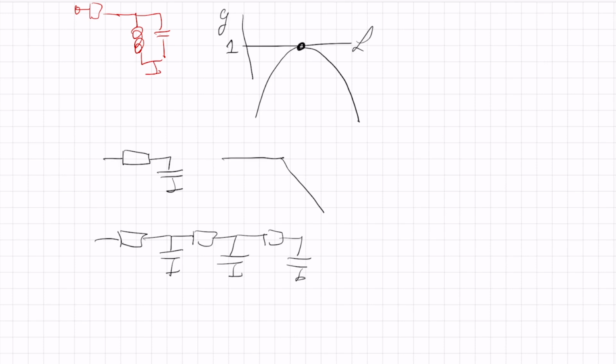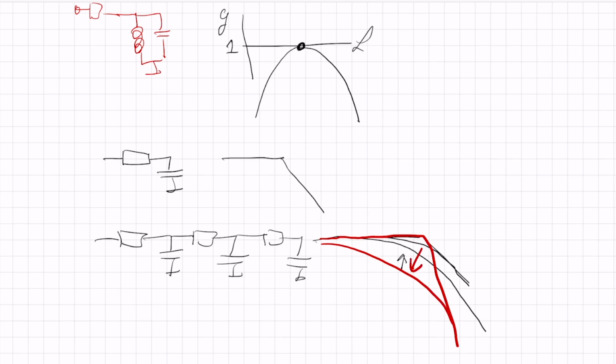But since a first order filter has a roll-off like this, if you cascade 3 of them, you get in the end a steeper slope, but it also takes a shortcut. It's not very sharp. So what we like for these filters is to be like this and then go steep. But if we just cascade a few first order filters, we get a really round response. And here my wanted signal is attenuated and I can correct for that, but then I need extra bits in the digital domain, and that's not good.